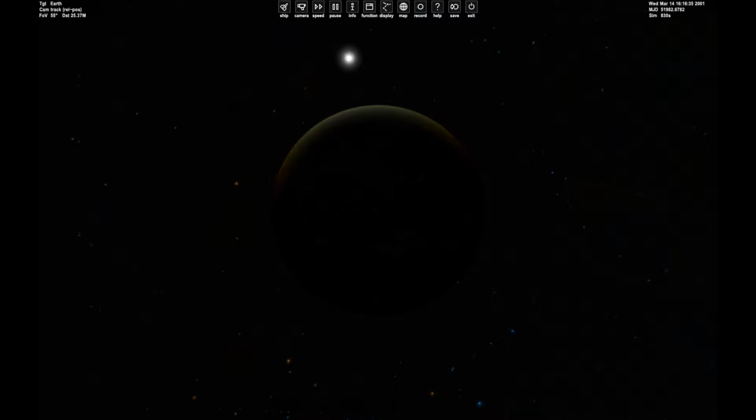So we can even find information about our craft, GL01S. The mass is 26,700 kilograms, roughly. The dry mass is the emptiness, and the propellant mass is how much propellant is loaded on board. These two numbers are very, very important if you want to do... actually, it doesn't matter for the Deltaglider, and I'll explain why in a minute. But if you want to do it with the other crafts that don't solve the equation for you, very useful.